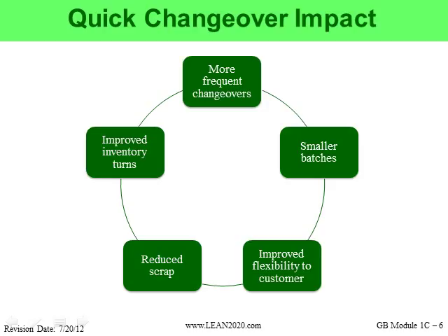Years ago, I had an operation where we had film on a laminator used to coat 2 sides of a printed circuit board. We'd run a panel through there, through this machine, and based on the width of the panel, we had a different size film on that laminator. So we'd coat film to the top and the bottom of this panel.